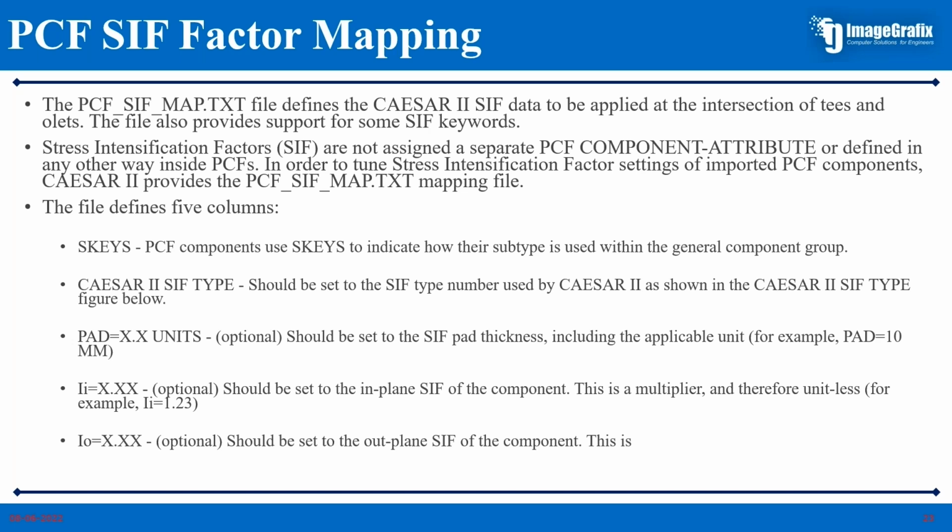So when you are specifying your PCF component for any of your SIF factors to be entered, it could be for your Ts, it could be for your bends or anywhere. S keys will be playing a major role here, followed by the CAESAR II SIF type against that S key, followed by, if it is for a T component, what should be the pad units, pad thickness or pad thickness units. Then the in-plane and out-of-plane SIF values can be provided, and you can work on the details straight away.